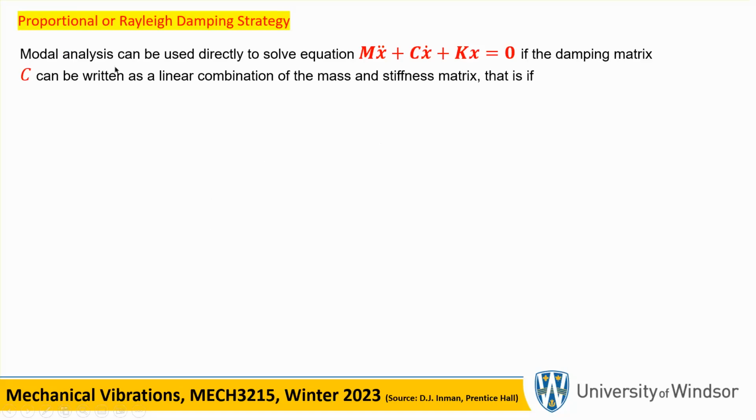although this modal damping is fine and it's widely used in practical applications, there is an alternative approach called the Rayleigh damping strategy. Another word. Now notice that first of all, M and K, if I ignore damping, if I ignore this middle term, I can make a transformation in which M becomes diagonal and K becomes diagonal. That's what we did on Thursday, and I did earlier today.